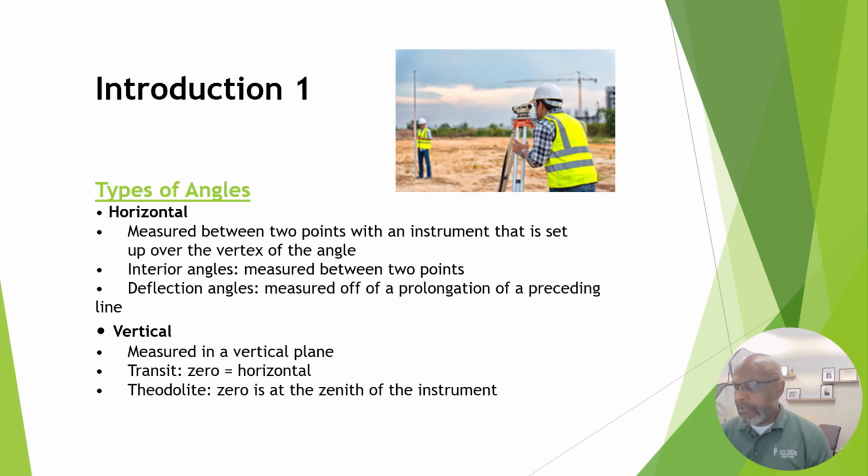When measuring a vertical angle with a transit, a theodolite, or a total station, the angle is from the 0 point of the circle to where the horizontal crosshairs intersect the point where the vertical angle is desired. The method of vertical angle measurement will vary with the type of instrument used.